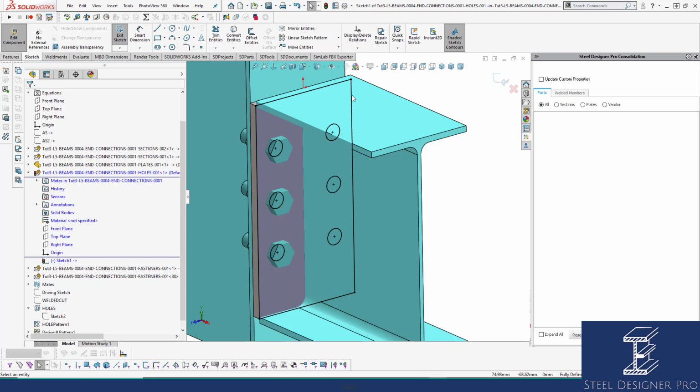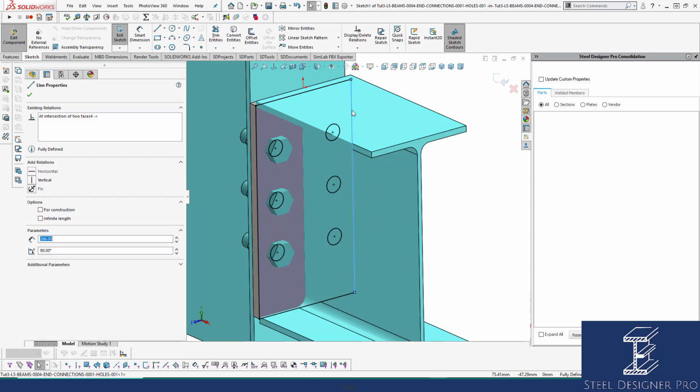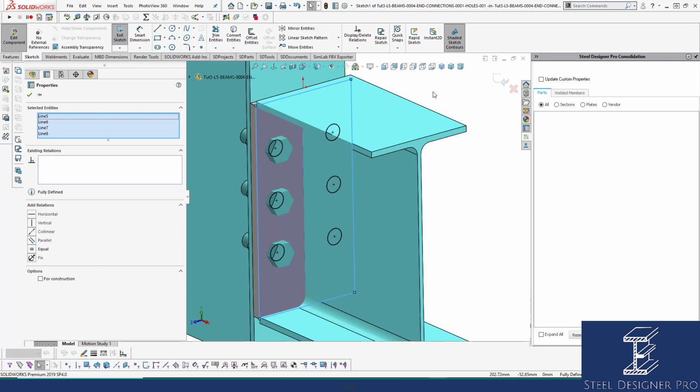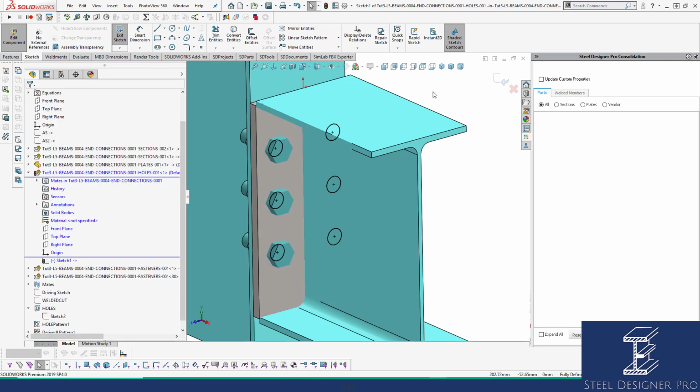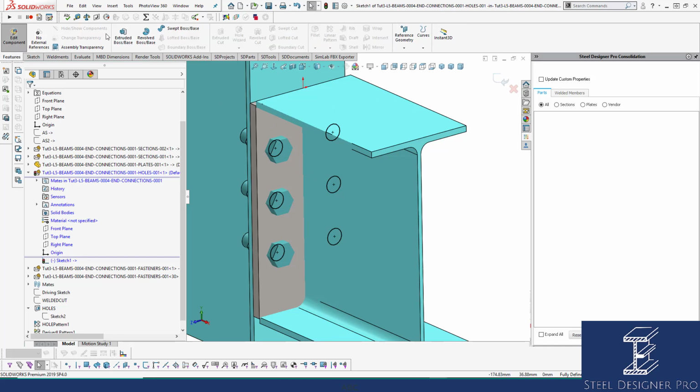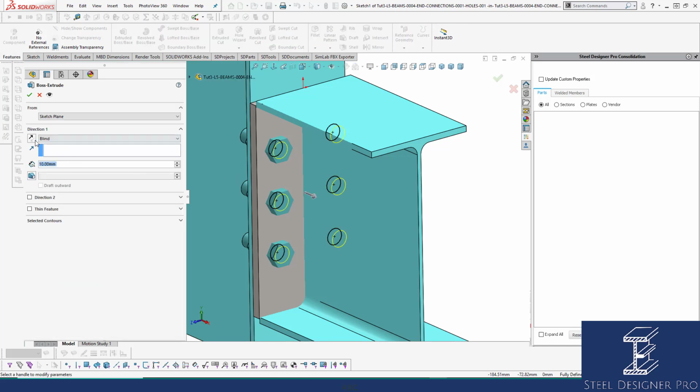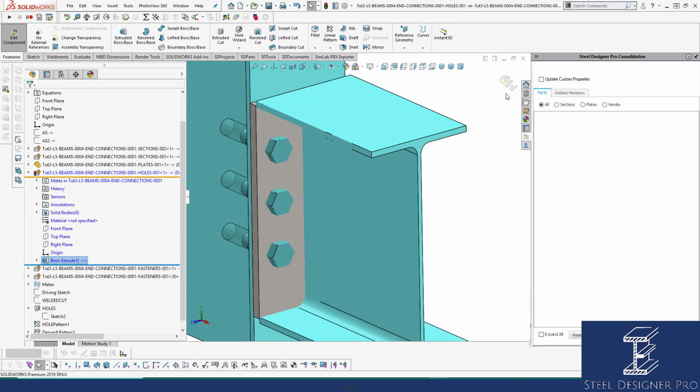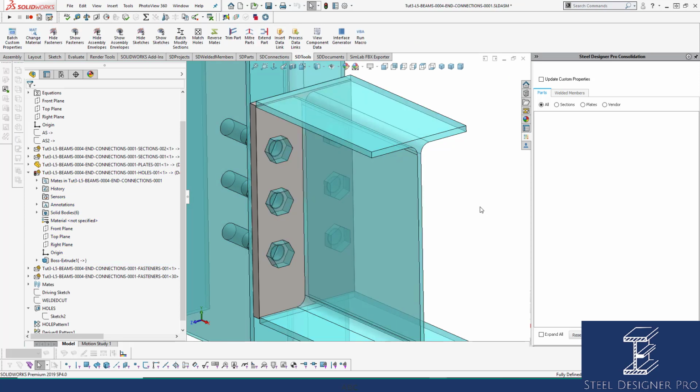Unselect my filter and you can see through the intersection curve it's selected the outside boundary. So if I was to go select chain and go delete, the only new entities that will pop up are now based on if I cut the plate or if I add new holes. So now I have done that. It's just as simple as going, let's create a boss extrude through the other side, and we will give it, say, 100 mil. And there is my hole component.